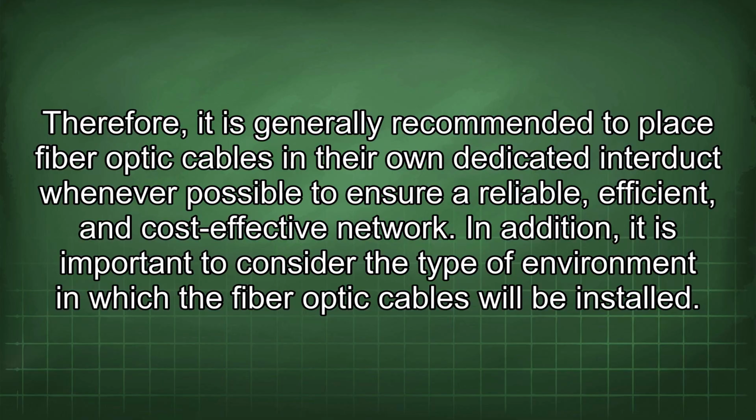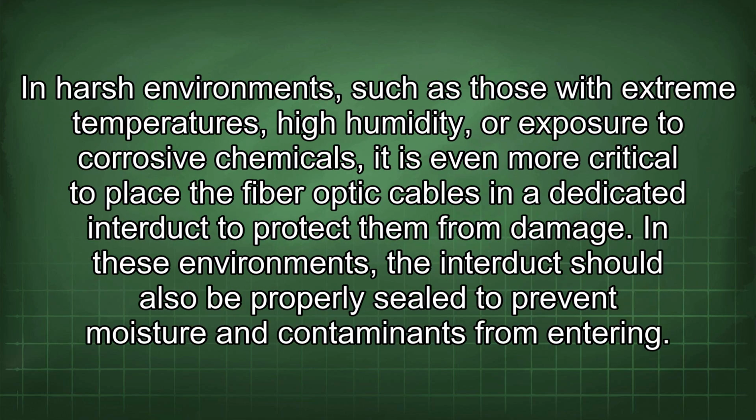In addition, it is important to consider the type of environment in which the fiber optic cables will be installed. In harsh environments, such as those with extreme temperatures, high humidity, or exposure to corrosive chemicals, it is even more critical to place the fiber optic cables in a dedicated interduct to protect them from damage. In these environments, the interduct should also be properly sealed to prevent moisture and contaminants from entering.